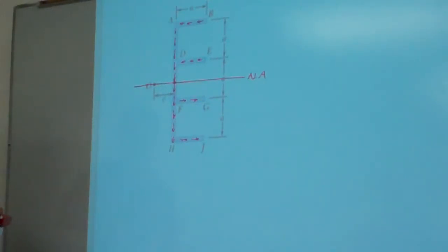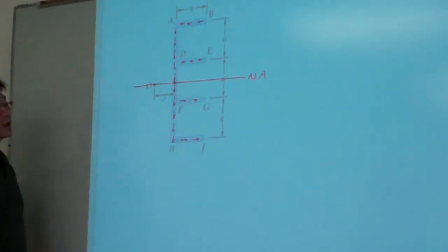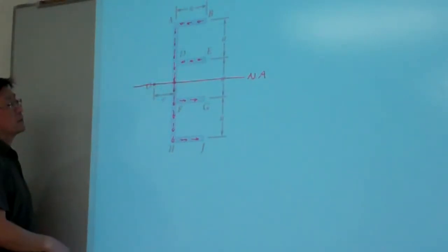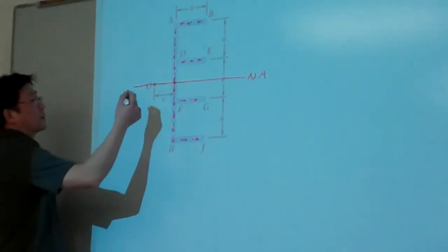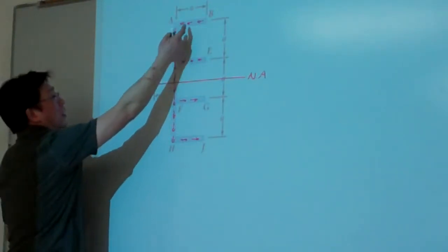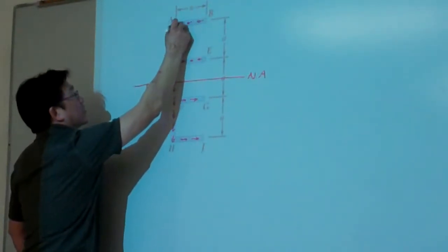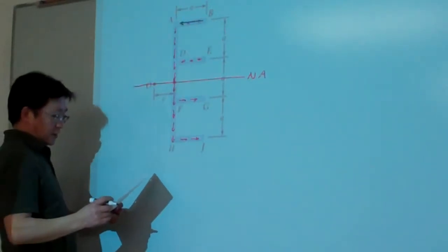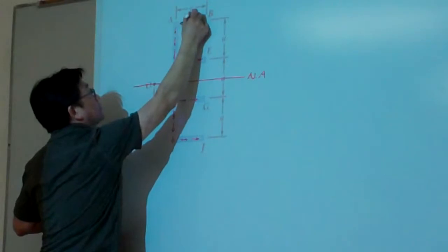So that is the first step to find the correct shear flow. Then we can calculate the shear stress. Basically, the concept is this: on the top here, let me make it equivalent to this force, and let me call it F1.